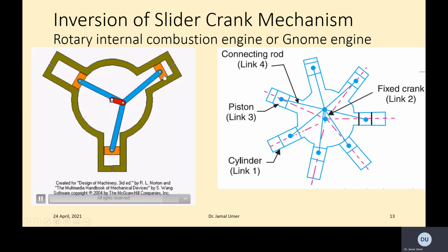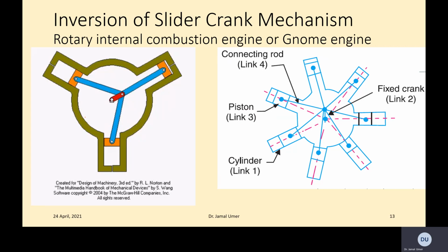And of course, because of typical multiple cylinder engines, you got different working cycles on each cylinder. So in one case, if you have the power stroke here, in another cylinder you will have a compression stroke. So basically they are helping each other. That's the principle of this rotary engine.